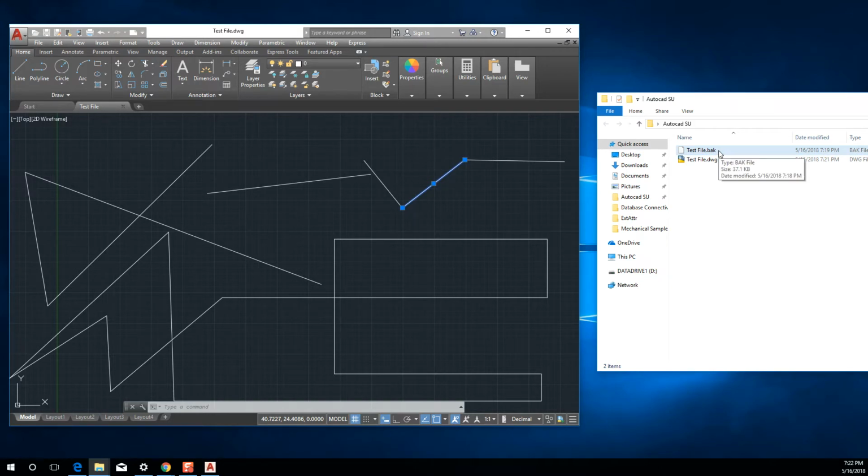These little backup files are very messy. I don't like having all these files in my file structure. It's very tempting to delete them, right? But don't do it. You'll regret it. Maybe at the end of a project when you're finished working, you're completely done, you know you won't need to access a backup anymore, you can delete them, but for the entire project, you'll want to make sure that you keep them.